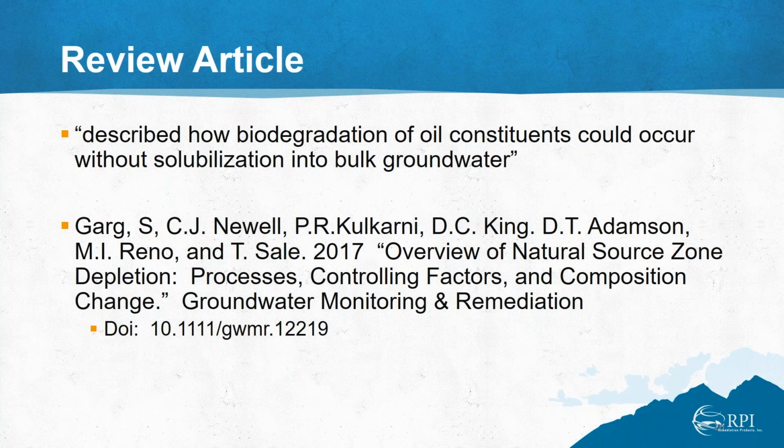So we are going to continue to monitor groundwater on a regular basis. We also, at some point, we haven't chosen exactly when that will be, but we hope to go back out and actually do soil sampling. We had extensive soil samples on the front end that helped us develop the design, so we knew what the vertical distribution of mass was, as well as the aerial distribution.